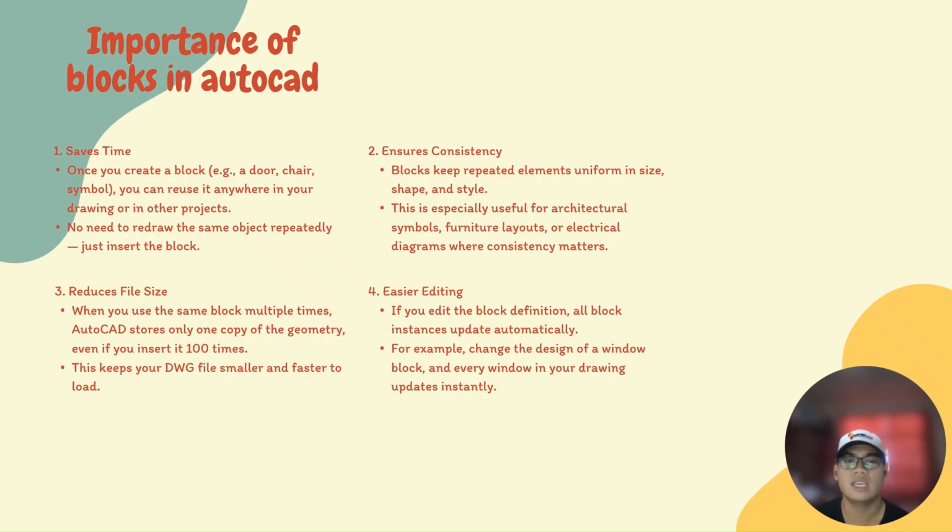Number four, easier editing. If you edit the block definition, all block instances update automatically. For example, change the design of a window block. Every window in your drawing updates instantly.